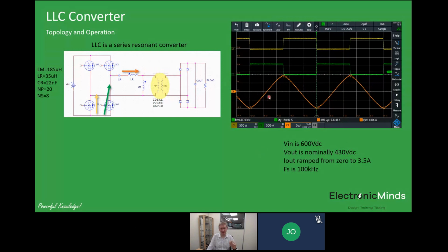Now, before I press go on this, I want to explain that this particular waveform you can see at the moment corresponds to a 0 output current on the output of our converter. If you probably can't read the scale, for channel 3 this is at 5 amps per division. So it's going plus and minus 10 amps for 0 output power. Now that might seem like a crazy thing to do, but you'll see why it gives you a benefit in a moment.